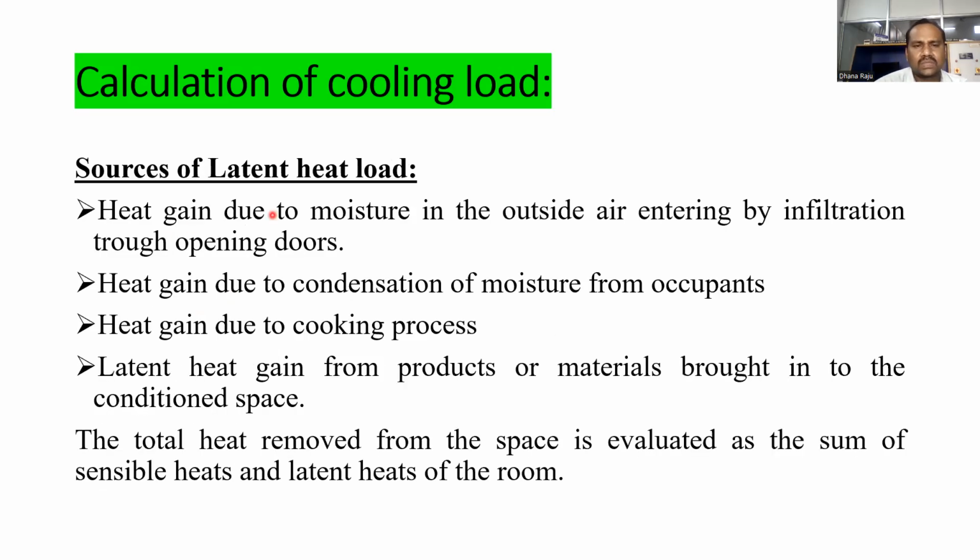Then we have sources for latent heat load. What do we mean by latent heat load? Whenever a heat interaction occurs that causes a phase change from liquid to vapor, vapor to liquid, solid to liquid, or liquid to solid, vice versa, then the heat interaction is called latent heat. During latent heat, the temperature remains constant. The important sources for latent heat are: number one, heat gain due to moisture in the outside air